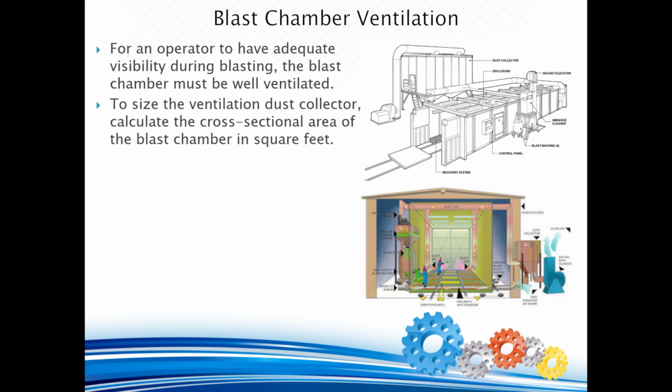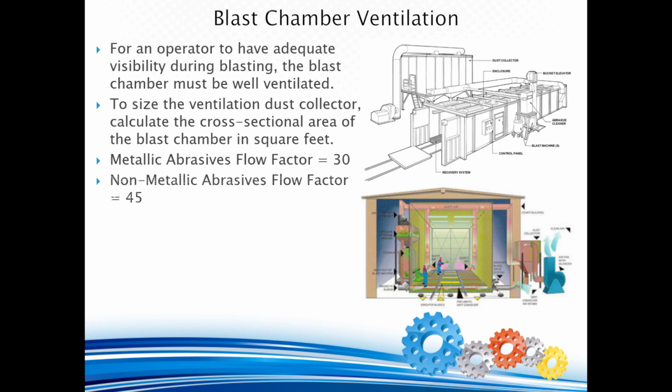To size the ventilation dust collector, calculate the cross-sectional area of the blast chamber in square feet. Next, multiply this figure by flow factor of 30 for use with metallic abrasives or flow factor 45 for use with non-metallic abrasives to get the required dust collector's CFM flow rate. Add 10% to the required flow rate if the blast room system will be used by more than one blast operator.